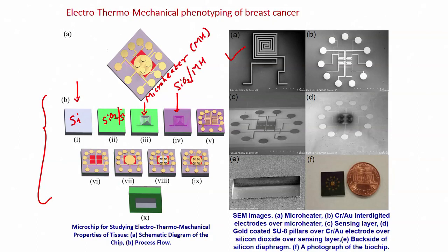You get it? Where are we right now? Silicon oxide, that is grown on silicon, on which we have, using photolithography, patterned microheater, okay. And then there is an insulator on microheater. The reason for placing this insulator is that next would be our interdigitated electrodes. You can see here, right, this step, but I cannot directly pattern interdigitated electrodes on microheater, because metal of microheater and metal of interdigitated electrode will get shorted, electrical short, right. So, to avoid this short, we are growing insulator on the microheater, and then we are depositing gold and patterning it using lithography to obtain interdigitated electrodes.